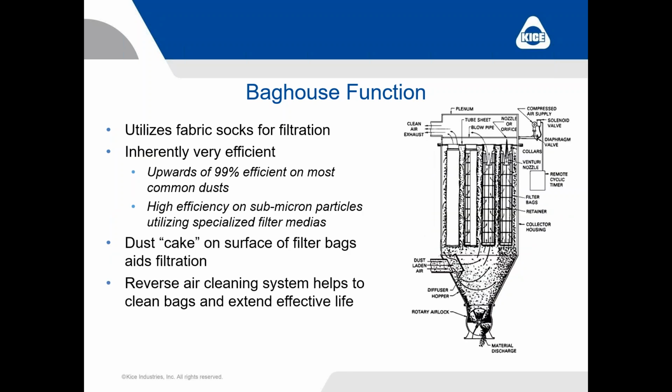So we know how a baghouse works. How do these filter socks work? Well, inherently, a baghouse is a very, very efficient air cleaner. Most common filter bags out there on the market are going to be 99% plus on most dust particles, say 15 micron, 10 micron, and larger is going to be a very, very efficient separation through these filter bags.